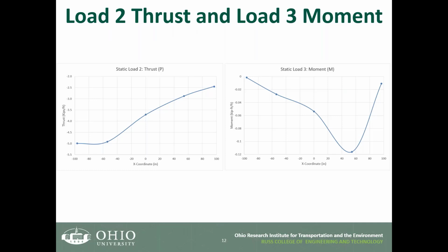So keep that in mind, because when Kevin explains the spreadsheet, he will discuss the interaction between the bending moment and the thrust. In many cases in shallow cover, the moment is dominant. But unfortunately, some of the software used for rating puts the thrust as dominant. No, actually the bending moment is the major impact. Go to the next.